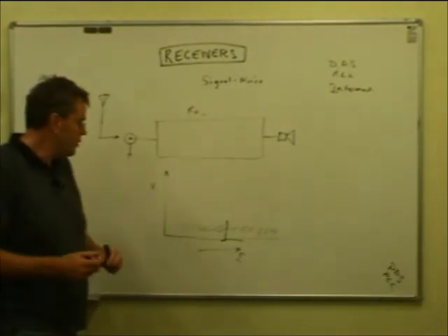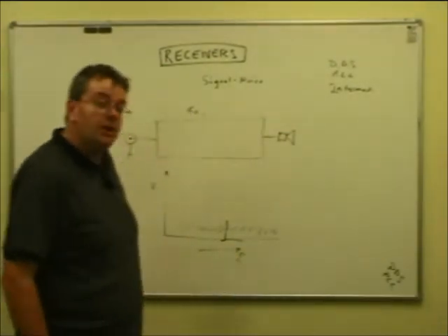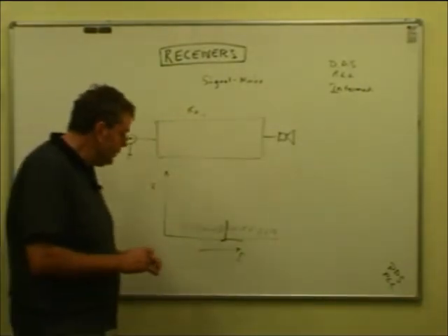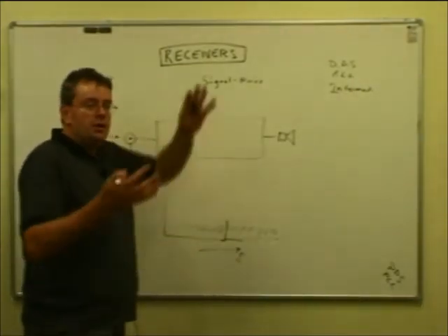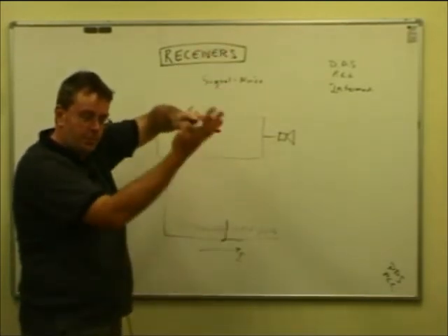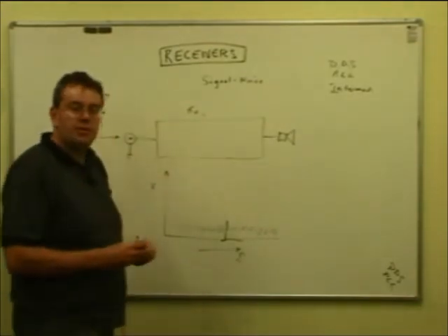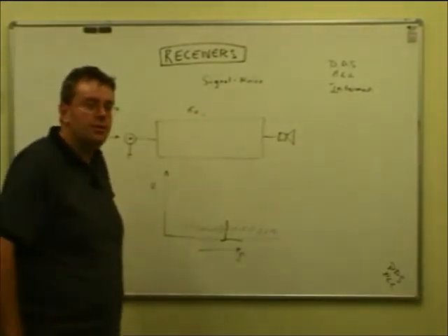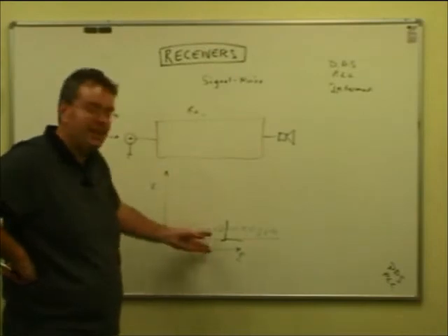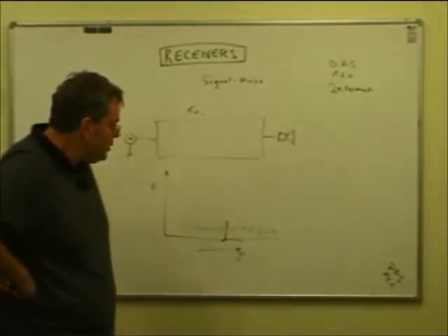You can express it in decibels, and we haven't covered dB yet, but you can come back to this if you like after that. So a very strong signal, the noise is very weak in comparison with the signal. It's a very big ratio, but a weak signal arriving at the terminals of the receiver, the signal-to-noise ratio is very poor, and it will sound noisy. You're starting to hear the background noise getting demodulated. Now, why is this important?